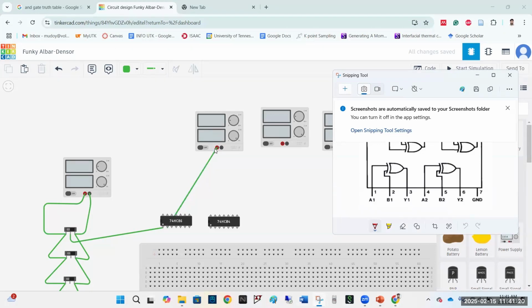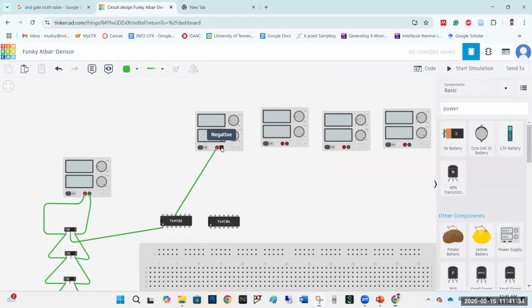The power supply will provide a certain amount of voltage in its positive terminal. Actually, we will provide 0 or 5 volt using this positive terminal. And what will we do with the negative terminal of the power supply? You can connect it to a common ground. We will make a common ground in the breadboard. Do you remember how the breadboard pins are connected?